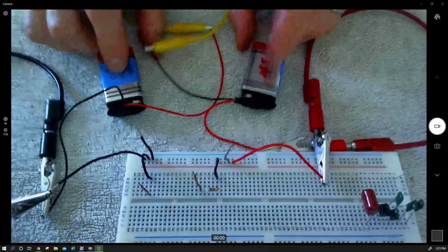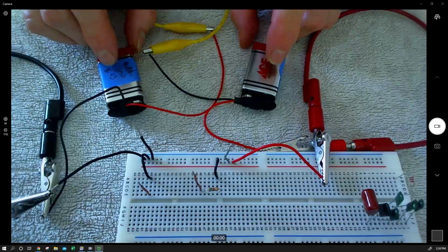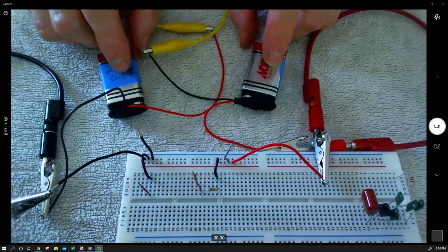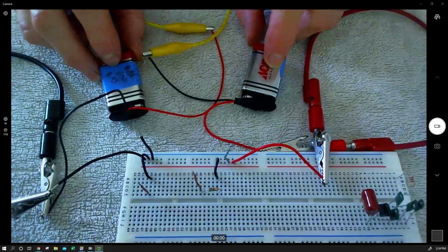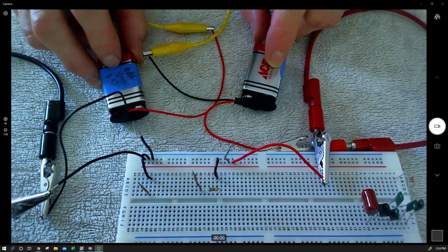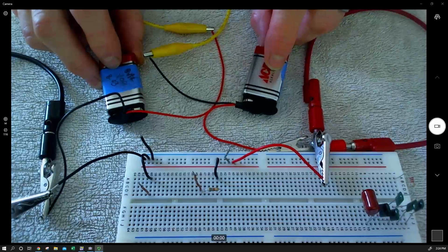Certainly if you are looking at portable sources like an electrochemical source, a battery type source, capacity will be important in having two parallel sources. Even if you have a fairly modest current and either one can supply it, having two, you will supply it twice as long. You'll have greater capacity.